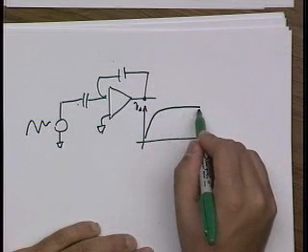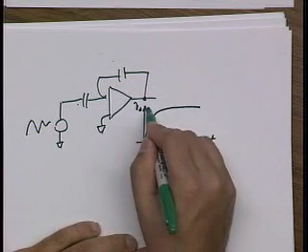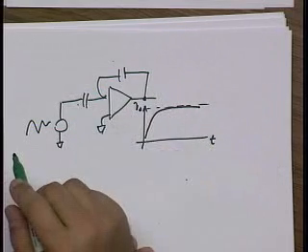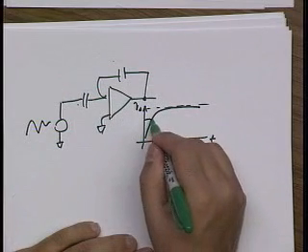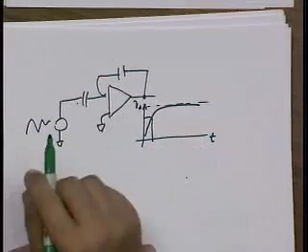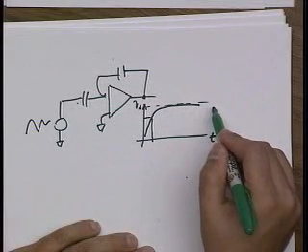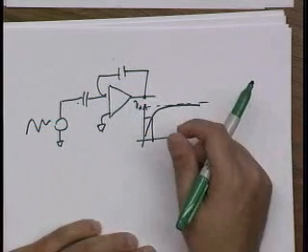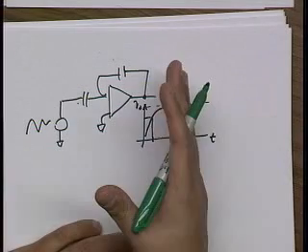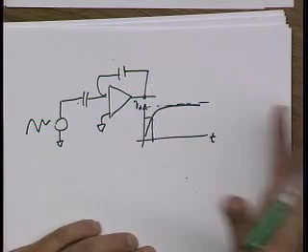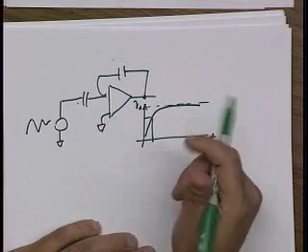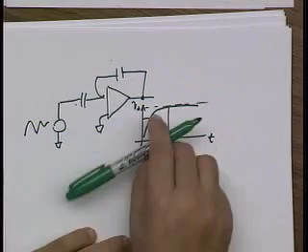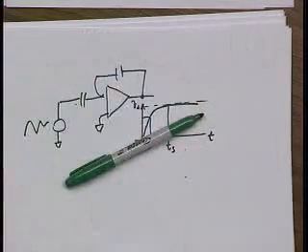And we have to wait for it to settle long enough so that we get close to the actual true value before we say that we're done with the sampling process, right? So if I stop right here, there's going to be a huge error just due to settling time. If I wait too long, basically I've wasted my time, because the quantization noise that I'm going to get from my A to D converter is going to be much larger than this settling time error that I would get because I didn't wait long enough. So there's pretty much a best point to stop. I should stop at a point where the settling time error is less than the quantization noise.